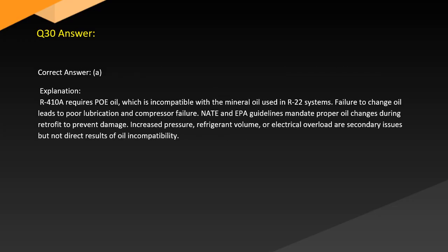Answer. Correct answer: A. Explanation. R-410A requires POE oil, which is incompatible with the mineral oil used in R-22 systems. Failure to change oil leads to poor lubrication and compressor failure. NATE and EPA guidelines mandate proper oil changes during retrofit to prevent damage. Increased pressure, refrigerant volume, or electrical overload are secondary issues but not direct results of oil incompatibility.